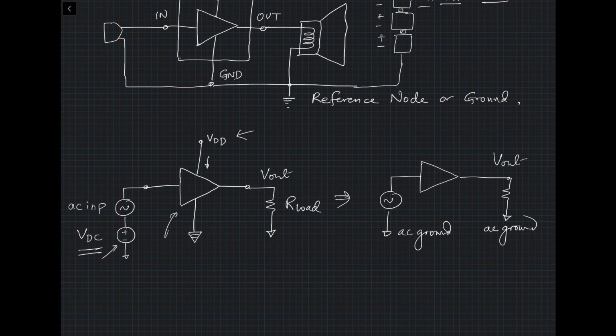From DC analysis, what you're doing is creating a model, a linearized model. We like to call it a small signal linearized model of your device or component, and then using that we can quickly tell how this circuit is going to behave.